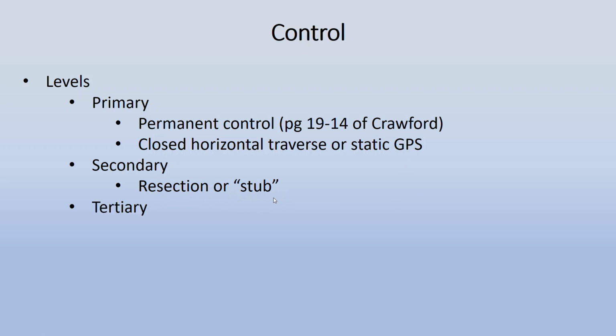And if you start building off of secondary points, then you're into your tertiary level, and that really becomes unusable for construction applications because you just don't have the confidence in its position to guarantee what you're staking is going to be where it needs to be.